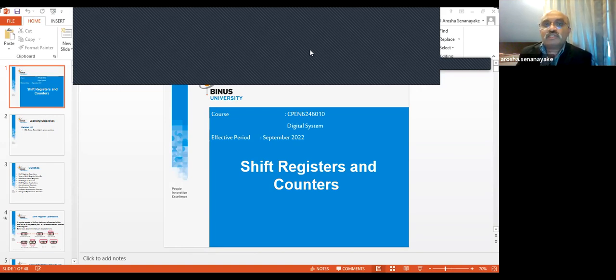So that really is shift right. In the same way, you will see the serial out, 1 bit at a time. The first data entered, 1, will be released from the data out. You know very well that in computer systems, 8-bit data is transmitted through 8 cables.